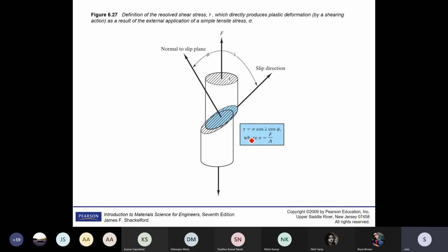But in plastic deformation, the dislocation moves by 1 atomic distance towards the slip direction. And it restores the lattice after slip. Because everything moves like a march past. You see, the military are doing a march past. If everybody moves 1 step forward, the formation looks the same.